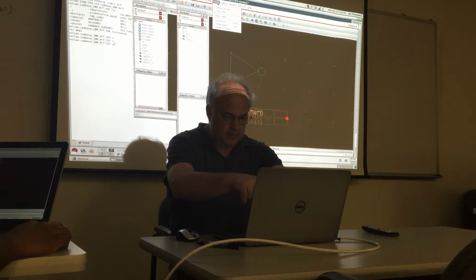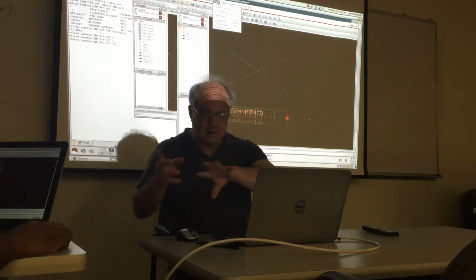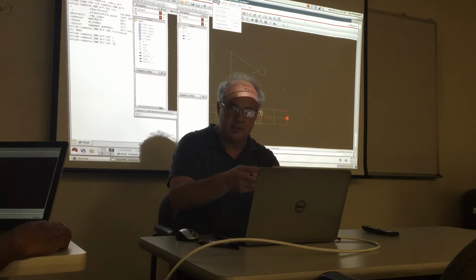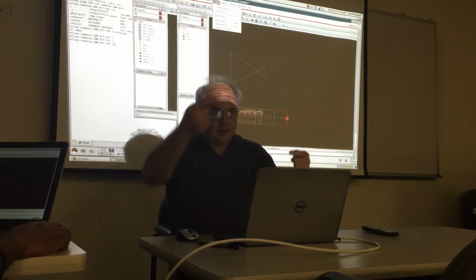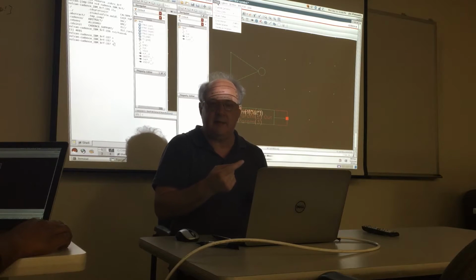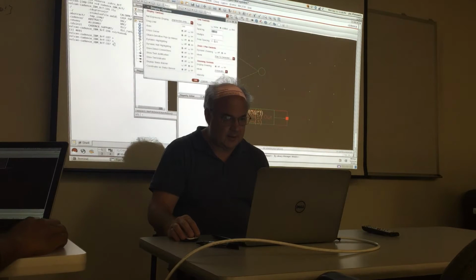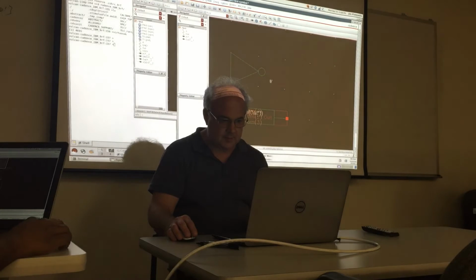If you left those at 0.0625 and 0.125, those are important here too. Because remember, you're going to be connecting wires to the pins on this guy. You'll see that we're going to move the pins up here in a second. If you don't have them on the grid, then you'll go crazy, because when you go back to schematic and create an instance and this symbol gets popped into your schematic, you'll try to get your wire over there and it'll never give you the ability to connect to the pin. So just make sure your display options are set to these values. It creates a real pain if you don't. I'm just trying to give you a fair warning.